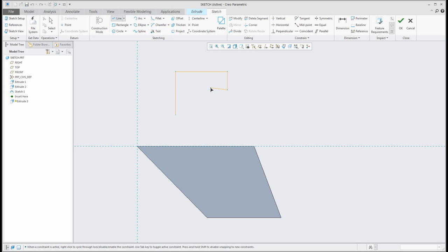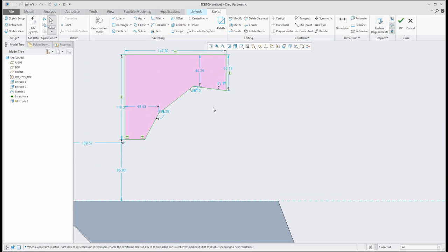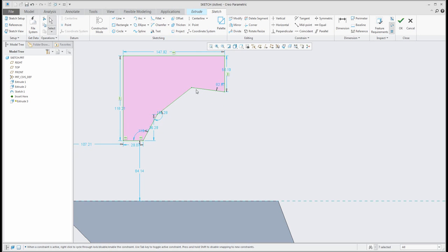For example, you would like to create a shape like this, but sometimes you make mistakes and you don't specify the correct placement of the point. That point I have selected and placed not correctly. It was not placed horizontally. So you can click the right mouse button and over there you have the function Set Horizontal, and that line will be created horizontally. Or you can select another line and set vertical. So you can work with constraints directly from the menu.